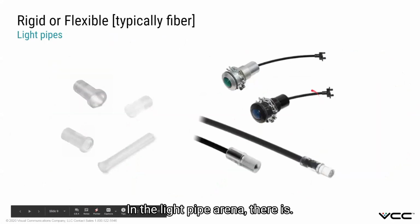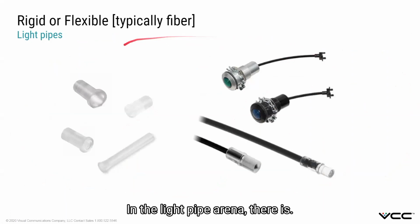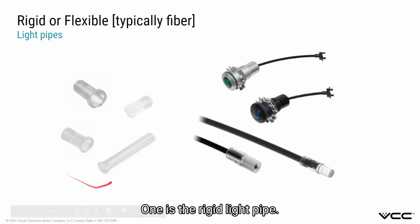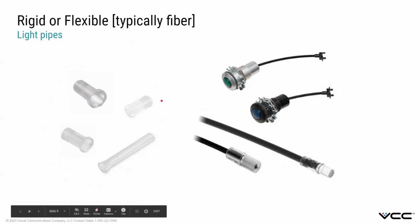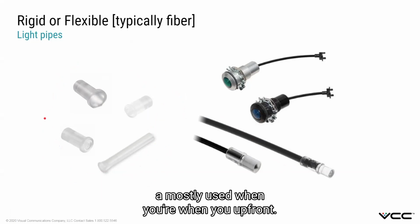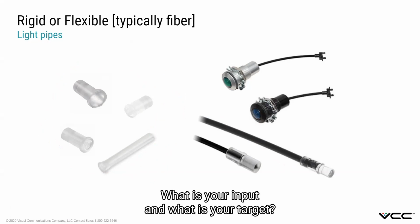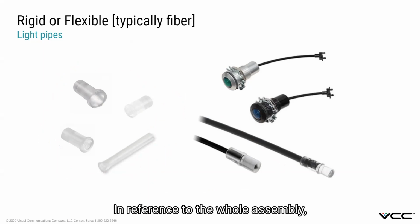In the light pipe arena, there are two types of light pipes. One is the rigid light pipe, and it's basically a molded part. These are mostly used when you know upfront, mechanically speaking, where your input and your target are, in reference to the whole assembly.